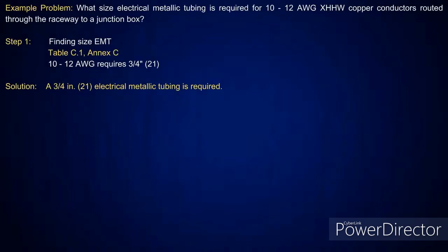And that gets you through your pulls as far as having a junction box. So you've got the straight pull and angle pull. Then what you're going to get into is sizing your conduits. Now, most learn this right away, but if all the conductors are the same size, you're going to look at Annex C. And then you're going to look for the type of wiring method that you're employing. At this point, we have electrical metallic tubing, so that's going to be Table C1.